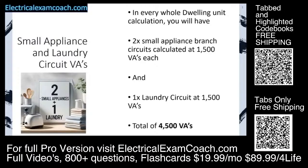Now this is something that we're only going to do and attach it to the general lighting load and receptacles before demand factors. We're only going to do it when we're doing a whole house load calc. We are not going to add it on to something like an individual dryer or an individual range. Those are calculated individually. This is only when we're doing a whole home load calc.